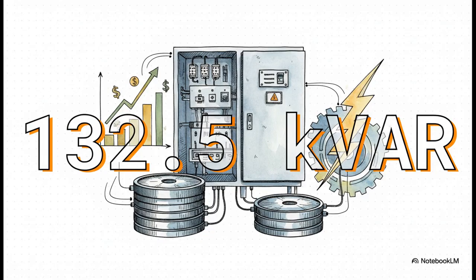So for a pretty typical 500 kilowatt facility, trying to get from that inefficient 0.86 up to a nice, clean 0.95, this is the answer the formula gives us: a 132.5 kVAR capacitor bank. See, this isn't just some random number. It's the specific, actionable solution to stop those penalty charges cold.